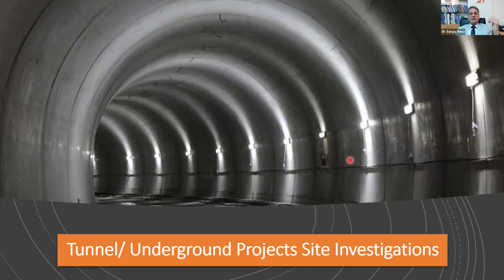So when we talk of tunnel or underground project site investigation, what is the right sequence? The right sequence, of course, starts with the available geological maps, satellite images, geological mapping. Undoubtedly, these are the starting points of the whole campaign. Then geophysical investigations, always invariably before drilling.